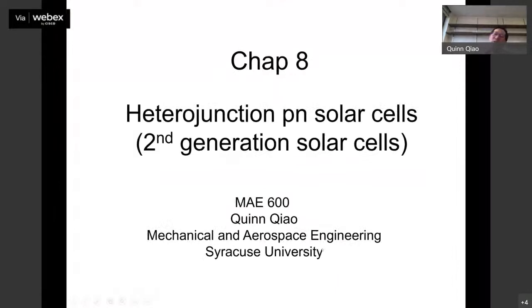So I'm not sure if you guys still remember, when we talked about the derivations, right? We thought that single crystalline silicon, crystalline silicon, polycrystalline silicon, these are first generation. Second generation will be thin-film solar cells. Thin-film solar cells, of course, include silicon solar cells, especially amorphous and nanocrystalline silicon solar cells. These are also second generation. But more frequently when people talk about thin-film solar cells, they either mean amorphous silicon solar cells or compound semiconductors, not large crystalline or polycrystalline silicon.